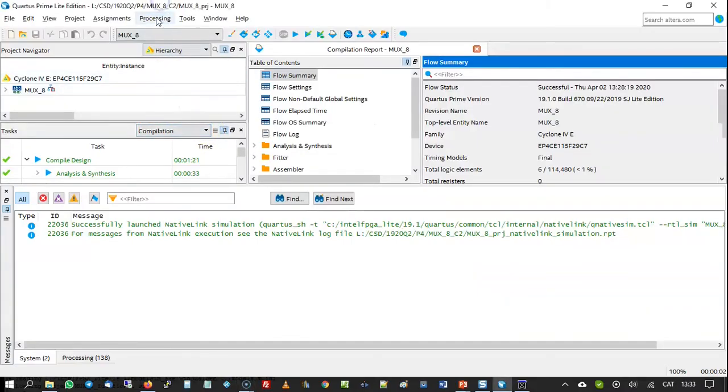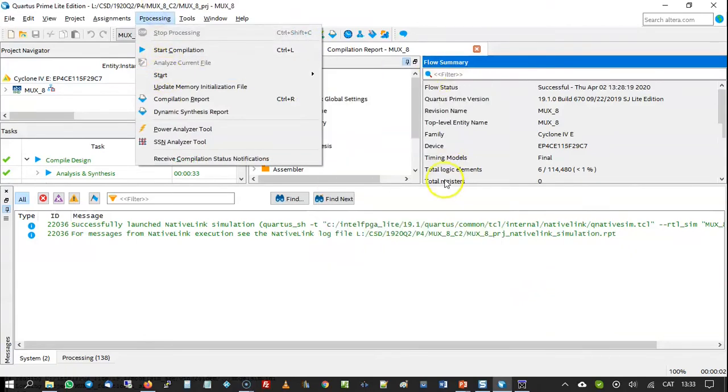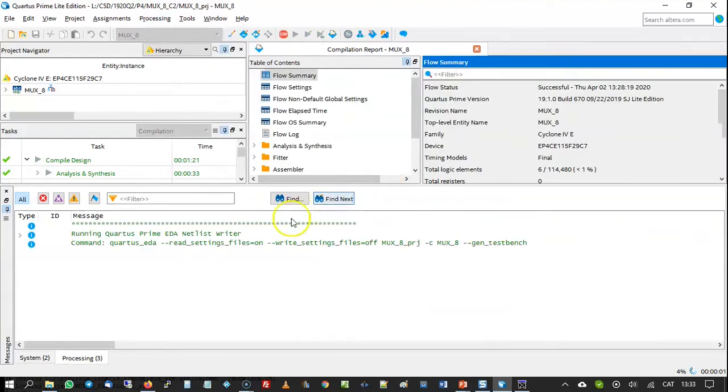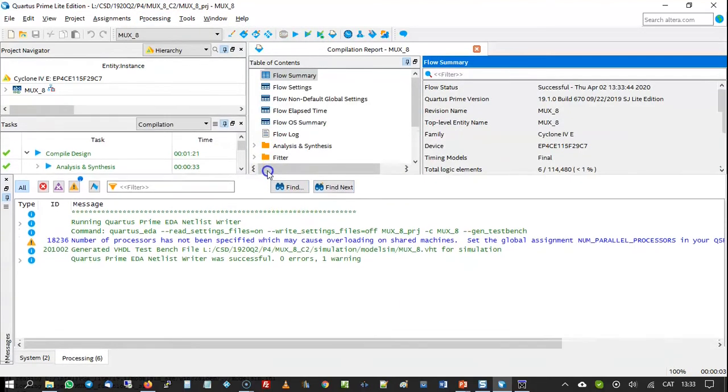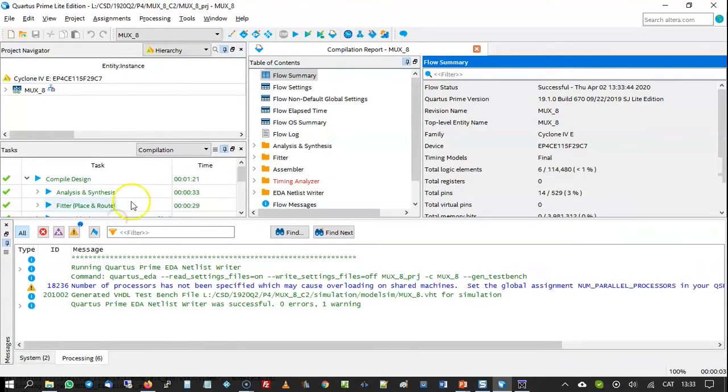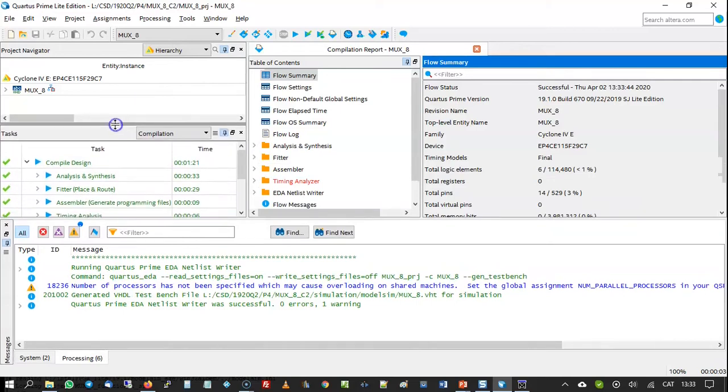So you have to go to processing and start a test bench skeleton. That test bench template writer is the key point for you, because it's going to convert the unit and the test and everything into VHDL. So that has been done right. Now it's your time to move the file into the simulation folder, okay? And then going back to the web and replace the empty processes with the ones that you've got as example in the web page, right?